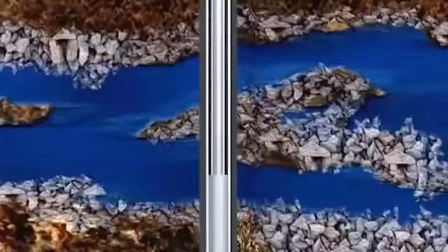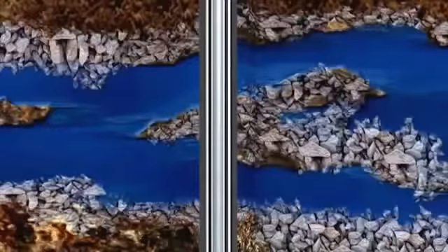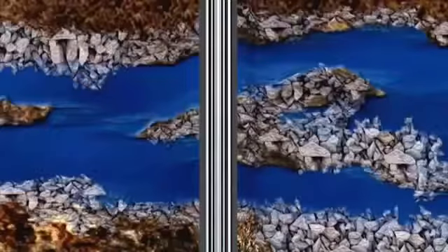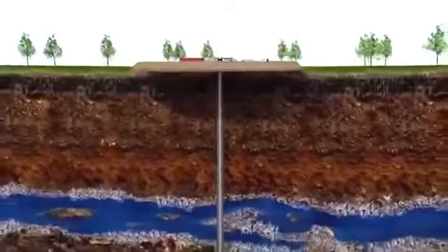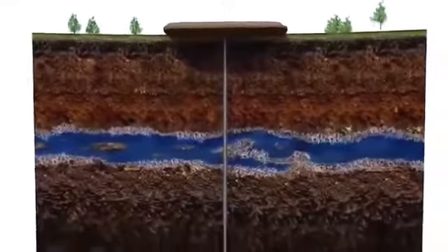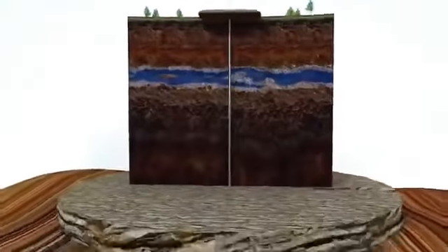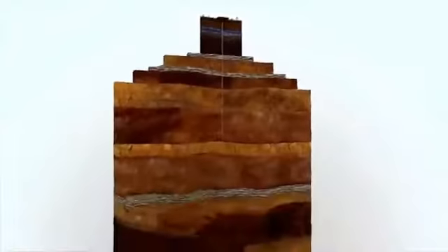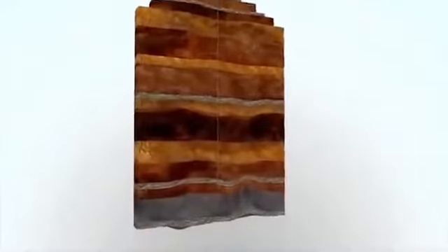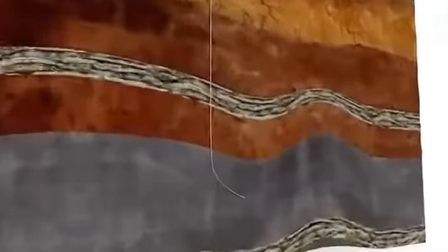In some cases, depending on the geology of the area and the depth of the well, additional casing sections may be run and, like surface casing, are then cemented in place to ensure no movement of fluids or gas between those layers and the groundwater sources. What makes drilling for hydrocarbons in a shale formation unique is the necessity to drill horizontally. Vertical drilling continues to a depth called the kickoff point. This is where the wellbore begins curving to become horizontal. One of the advantages of horizontal drilling is that it's possible to drill several wells from only one drilling pad, minimizing the impact to the surface environment.